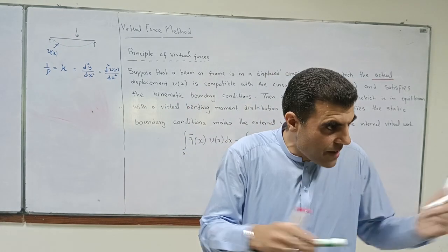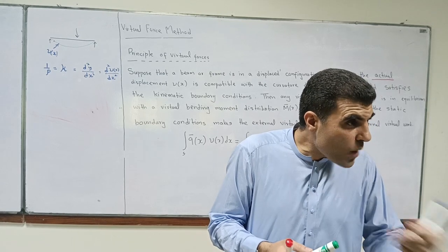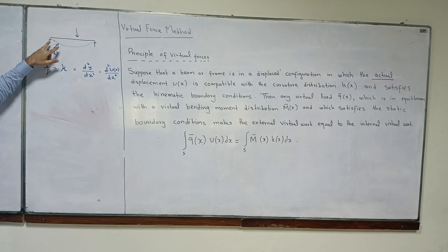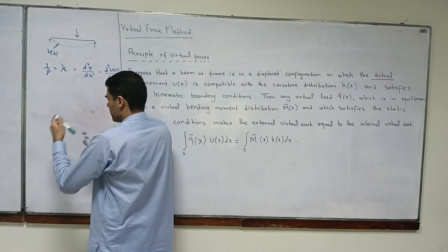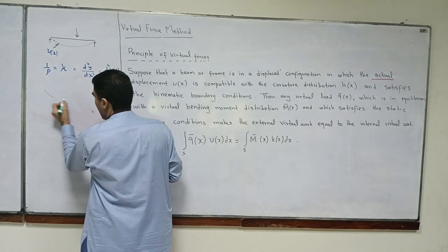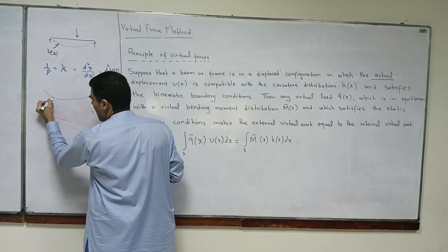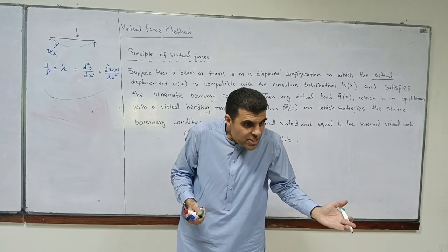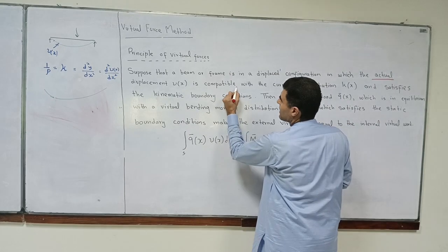If the beam breaks, if it cracks, okay, so your curvature, what happens? d2y by dx square, the change between the tangents, that you can't take. Why can't you take that? Because one portion of a curve, imagine, is like this and another one is like this. So at this point, how will I take dy by dx when these are not connected with one another? So I can't take d2y by dx square. So that is what's called incompatible.